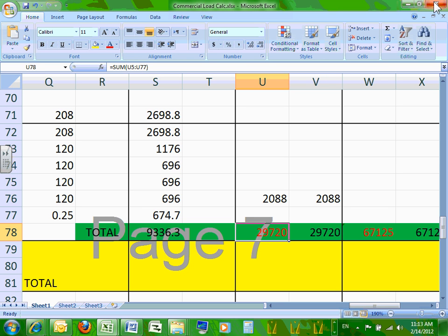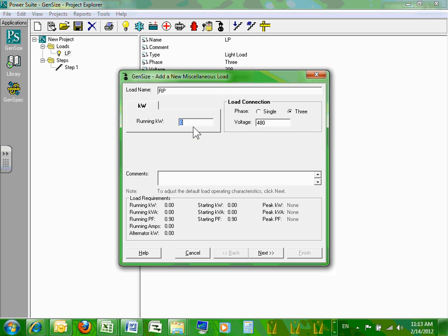Okay. All right, let's go here. And the only option that I have, first of all, let's change the voltage to 208. You don't have an option, but that's 30 kVA, kW, assuming the power factor is the same. So we put 30 kVA, kW. The only difference is what? The power factor. If the power factor is 95%, guys, you're off by what? 5%. We can live with that. Life is not perfect, remember. So 30, 208. Everybody got that? Okay, I'm going to go to next.